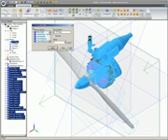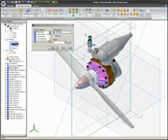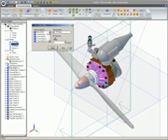In the Section View dialog, you can see the list of selected parts. Click once in the Slicing Plane box if it is not already active, if it doesn't have the focus, and select the desired sectioning plane. Click Apply. It may take a moment for the sectioning process to run to completion with an assembly consisting of several parts. There are a lot of calculations involved. When the sectioning process is completed, click Close.